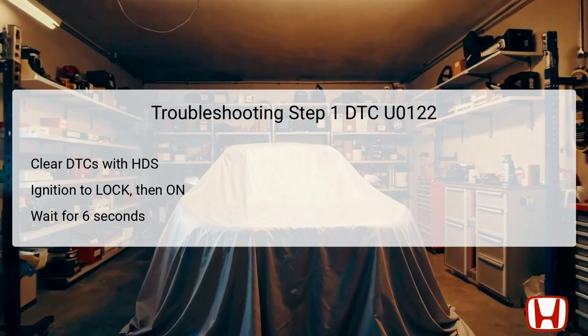A wait period of at least 6 seconds is recommended before proceeding to the next steps. This pause allows all modules to fully initialize, thus enhancing the accuracy of subsequent diagnostics. This step is foundational, as it provides a clean slate for the system to communicate and helps in identifying if the problem is persistent or intermittent. Completing this step prepares one for checking if DTC U0122 reappears after the reset.